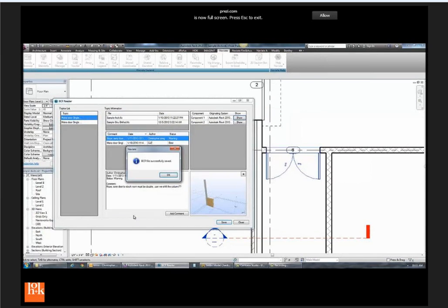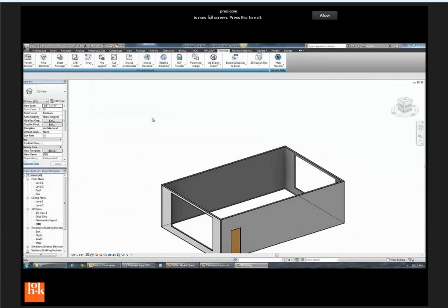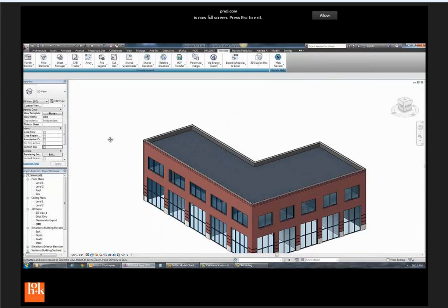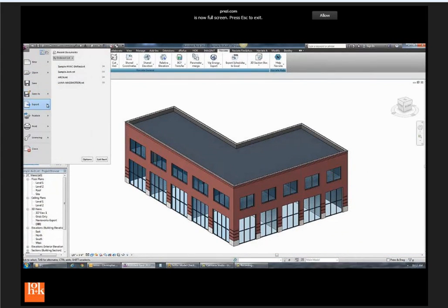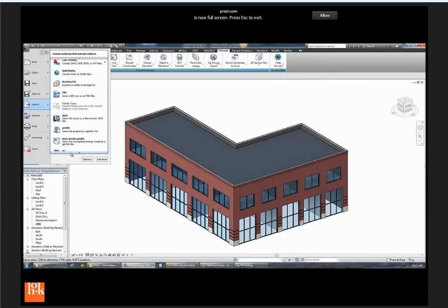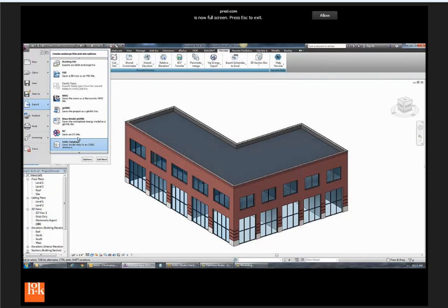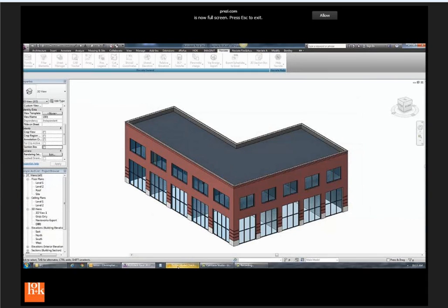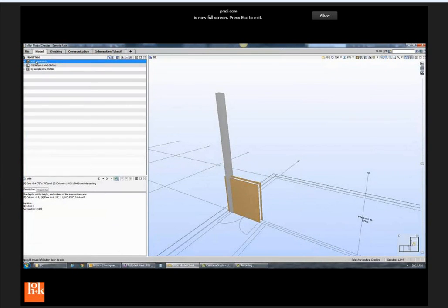And in addition to that, which is, we could just send them that, but I'd also like to send them the IFC file that's been updated. So we just dump that out. After I show everything here. Okay, so I'm just going to overwrite, just like you would do in Navisworks, I'm just going to overwrite that IFC file, just like you would overwrite NWC.